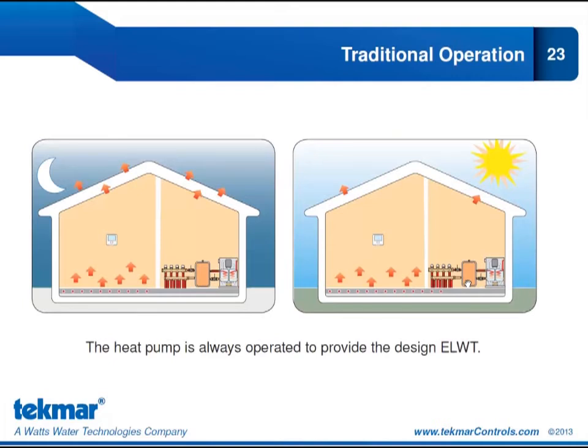So what's the impact of this? Well, we're going to see temperature swings. Our system is going to be operating at high water temperatures for a short period of time to satisfy the thermostat before it turns off again. So we're going to see an overshoot, and then we're going to suddenly turn that system off until we drop below set point, so we're going to see that undershoot. It's an inefficient use of energy. We're going to have the on-off cycling of our heat pump and the equipment. And because we're delivering that high water temperature when we don't need to be, we're going to experience expansion noises.